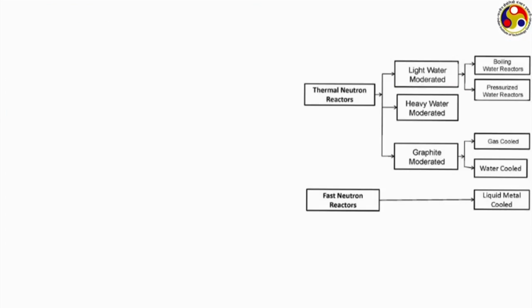Now, nuclear reactors can be classified into different categories as well. Actually, from now onwards we are not going to use the term heterogeneous, because we are going to talk only about heterogeneous nuclear reactors. And heterogeneous reactors can have several kinds of classification. One common classification is based upon the neutrons that are being used inside. So, based upon the neutron flux profile, we can have fast neutron reactors or fast reactors, and thermal neutron reactors or thermal reactors. Fast neutron reactors of course utilize fast neutrons for their operation, and hence they must use a fuel which has some significant value of this fast fission cross section.